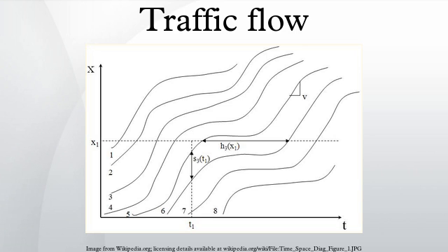A more general definition of the flow and density in a time-space diagram is illustrated by region C. Congestion shock wave equals. In addition to providing information on the speed, flow, and density of traffic streams, time-space diagrams may illustrate the propagation of congestion upstream from a traffic bottleneck. Congestion shock waves will vary in propagation length, depending upon the upstream traffic flow and density. However, shock waves will generally travel upstream at a rate of approximately 20 km per hour.